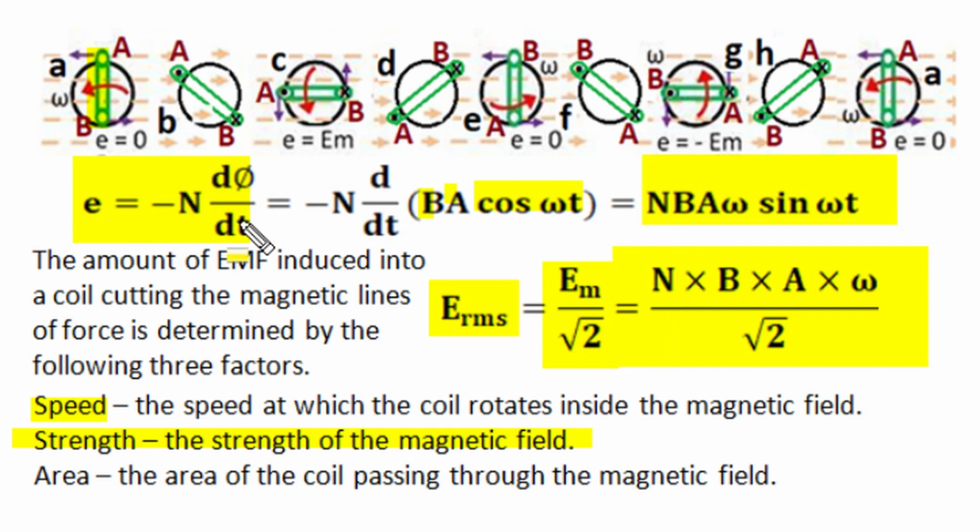The higher the number of turns, the higher the EMF, and this EMF also depends upon the area of the rectangle loop. Higher area would have higher flux linkages and higher rate of change of flux linkages, or higher EMF. So induced EMF is directly proportional to number of turns, strength of working magnetic field, area of loop and rotating velocity of loop.